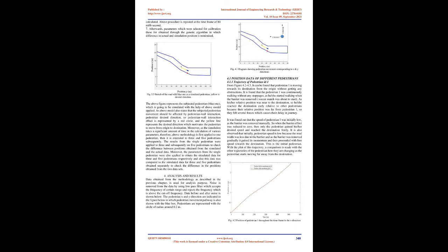Therefore, to make the model more effective, it is improved by some researchers, and it is assumed that there should be some proportionality between the repulsive forces acting on a pedestrian and its desired velocity. Thus a pedestrian tending to move with high velocity feels intense repulsive actions. By means of the parameter, the strength of the force can be adjusted while the diameter of pedestrians depends linearly on the velocity. This incorporates the dynamic space requirement of pedestrians, modeling the fact that faster pedestrians require more space than slower pedestrians.